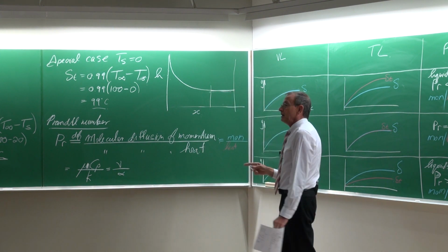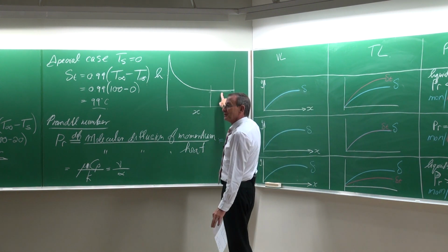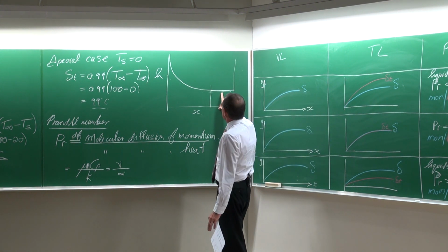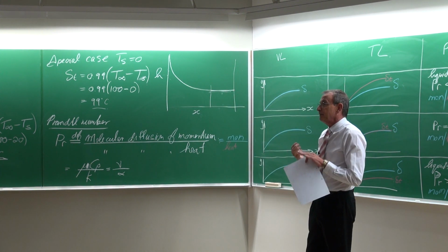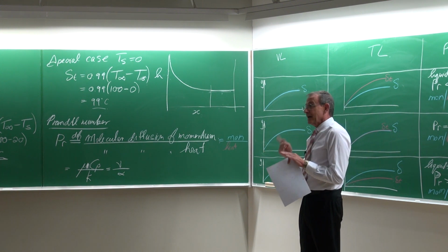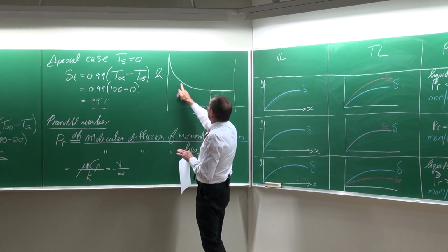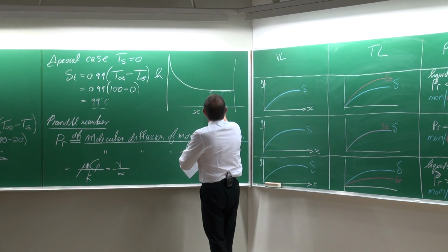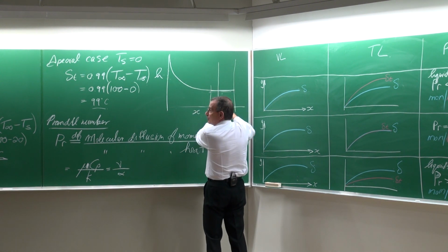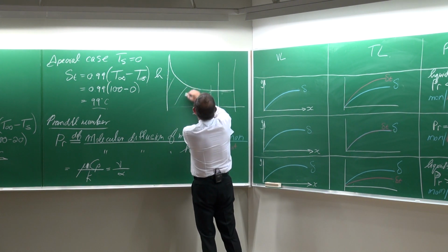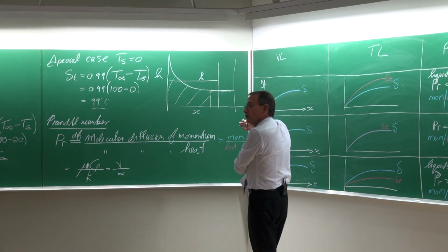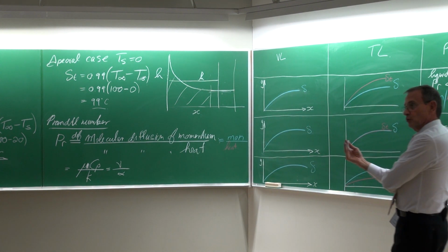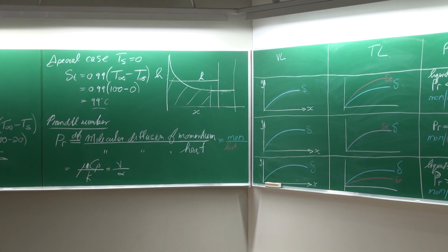And you will ask why? Well, the reason is it's more conservative to use a smaller one than maybe the average one. But again, if you want to be competitive in designs, then it is very advantageous to know exactly what happens, because then over a certain length of your heat exchanger, you can better determine the average value, which would be higher than the conservative value of fully developed flow, which means that most probably you can have less area, less material, less cost.